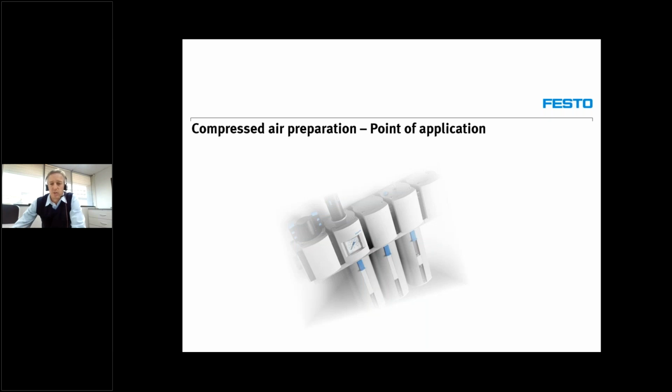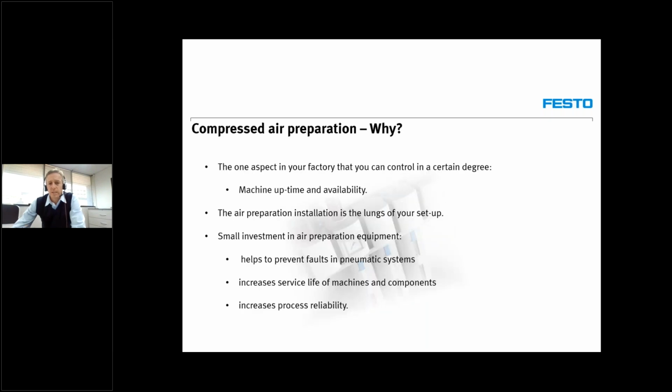It's always a trade-off between an initial investment in a proper air preparation system or continuous and often unforeseen expenses on breakdowns of equipment due to poor air quality. Now, why is it important to have clean and good quality air? Believe it or not, one aspect in your factory that you can control to a certain degree is machine uptime and availability. The air preparation installation is the lungs of your setup, and remember, the body can only be as healthy as the lungs. That being said, a relatively small investment in air preparation equipment helps to prevent faults in pneumatic systems, increases the life of machines and components, and increases process reliability.